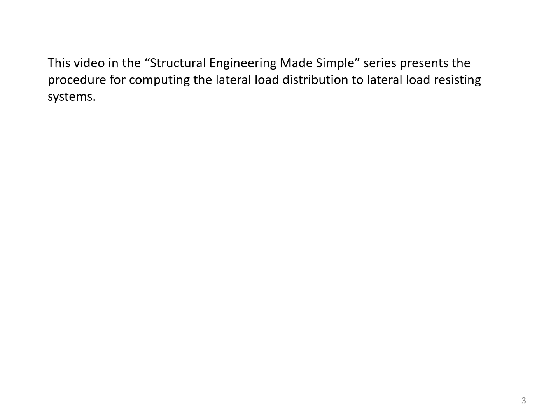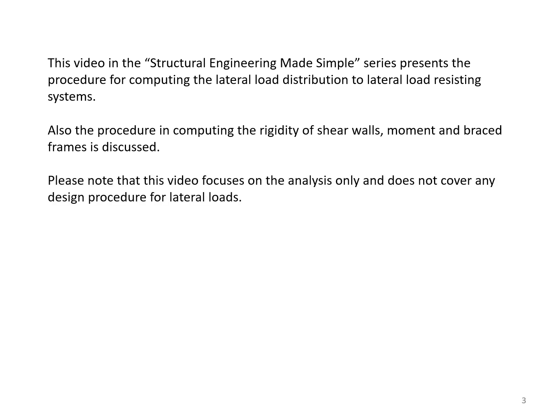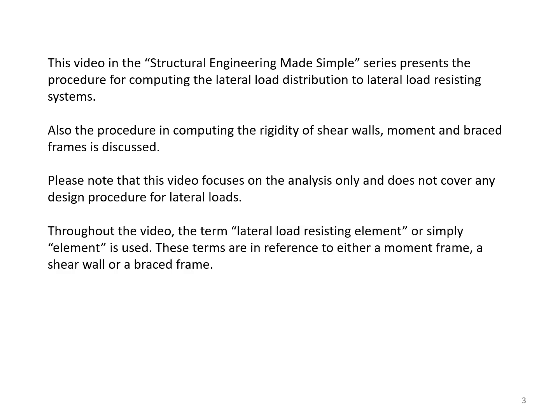This video in the Structural Engineering Made Simple series presents the procedure for computing the lateral load distribution to lateral load resisting systems. Also, the procedure for computing the rigidity of shear walls, moment, and brace frames is discussed. Please note that this video focuses on the analysis only and does not cover any design procedure for lateral loads. Throughout the video, the term lateral load resisting element, or simply element, is used. These terms refer to either a moment frame, a shear wall, or a brace frame.